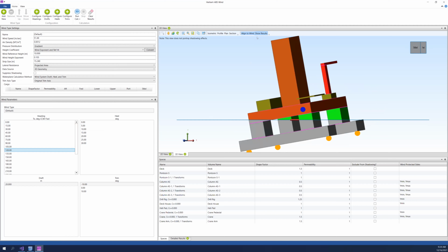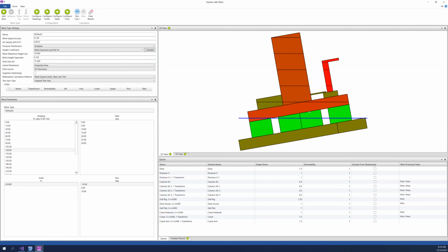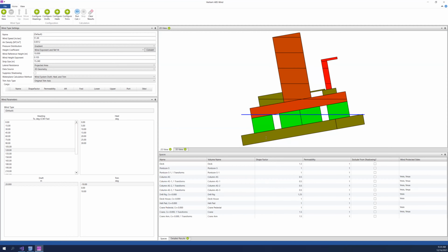We can have the show results behind it to show the 2D results, just so we can look and see if there's any overlaps missing, or if our 2D profile, say, had an extra rectangle here, we'd look at why that is to see any errors in our analysis. From here, the overlay looks good. We don't see anything coming out from behind with the 2D view. The 2D view is also available here, just on its own, to show the different polygons and the silhouette that we're considering for the hull.